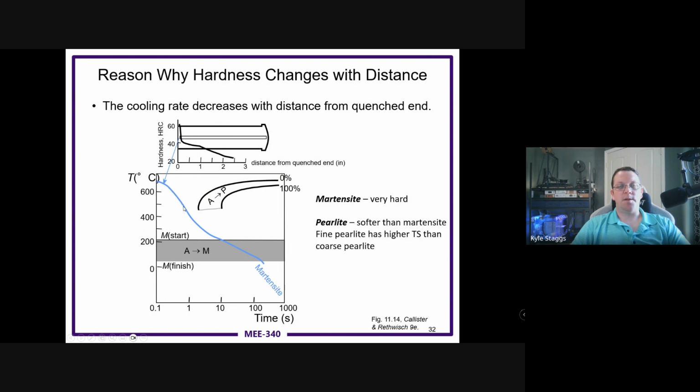It's going to be pulling down that temperature pretty linearly overall, and it's going to go through this phase. So it's not going to get into as much of the pearlite curve, but it is going to spend a lot of time growing martensite, and this is where most of that time is going to be spent in terms of actual cooling rate.